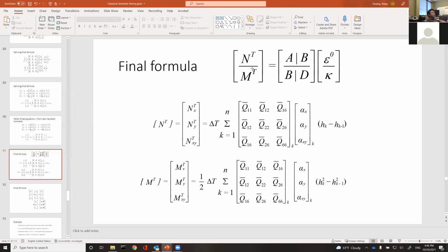These are not true loads. These are hypothetical loads. These allow you to solve these 6 variables in a 1 by 6 vector. This represents what happened to the laminate once you cool from a certain high temperature by delta T to another temperature. K is warping. Epsilon is the stretching or shrinking of the laminate. So just by solving this vector, you can tell how bad this laminate will warp due to the thermal stress.